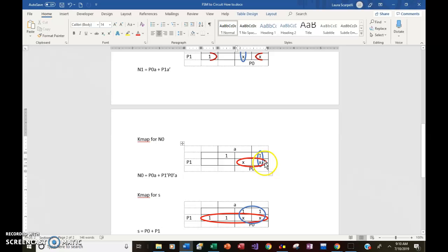I've plotted our don't cares as well. And as you can see, in the first one, the blue circle here, it works to our advantage to have a 1 here. Let's see if I can get in there and change this to a 1. But in the case of this one here, this X, in the red circle, we don't need the red circle. The red circle will create another term. So I will interpret this one as a 0 and remove this circle.